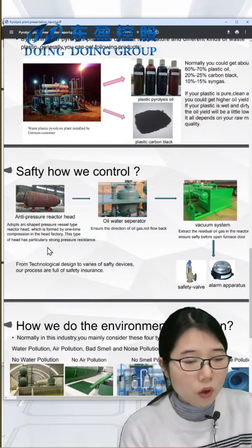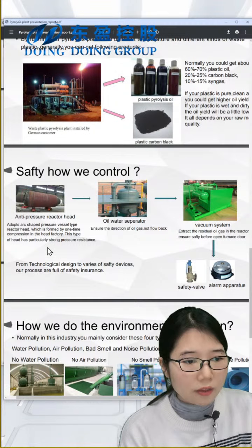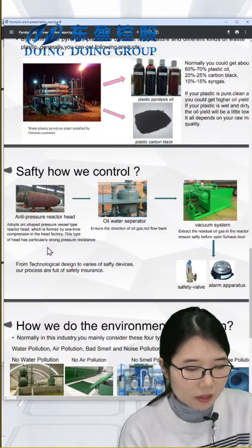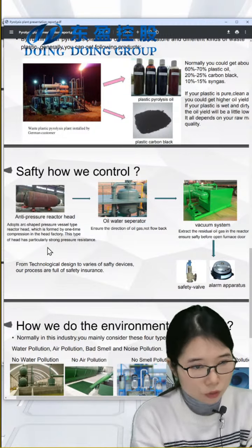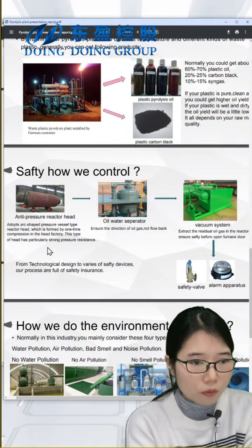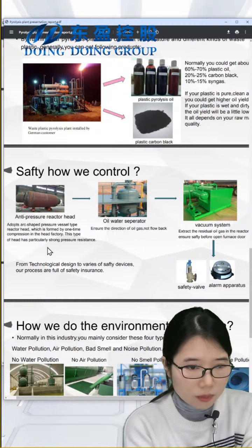And also we put in a safety valve. So when running the machine, if the pressure gets too high, the safety valve will relieve the pressure immediately and automatically.